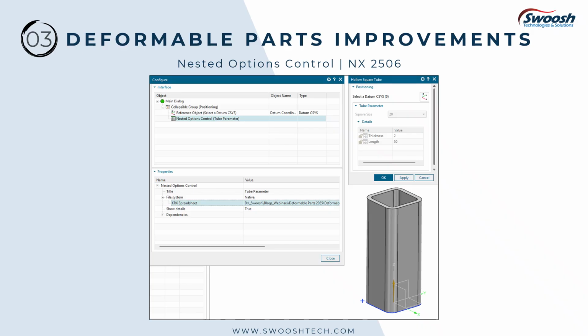With the June 2025 release of NX, this new nested options control is perfect for situations where you have a set of options that depend on each other, where a selection in one option menu drives changes in the available options in the menu below. In the past, we've been able to do this in templates using list expressions and some expression logic, but with this new technique, using a spreadsheet will create a set of option menus very quickly.